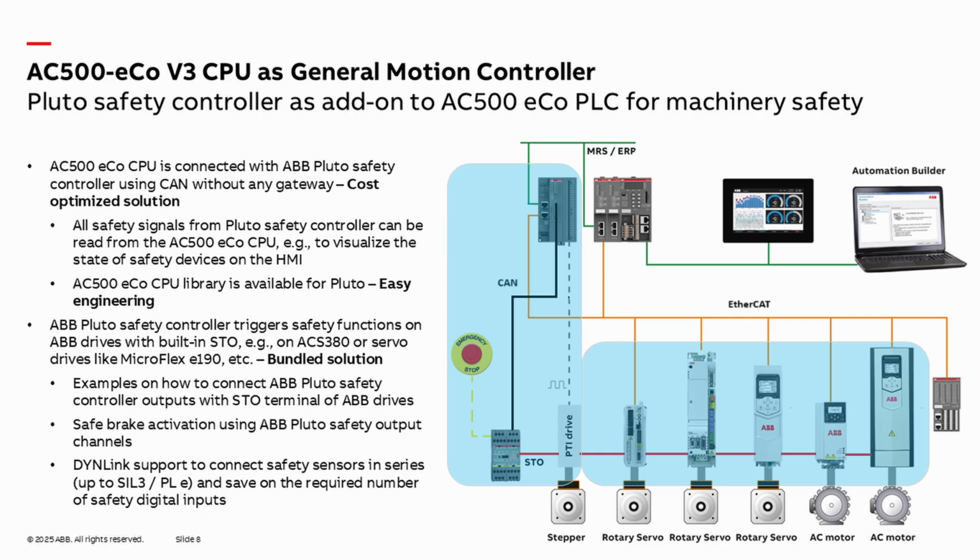So what we see here is completely new, because before you would normally need a gateway if you would like to map the states of the safety signals to the non-safety CPU, and then of course usually you would visualize them somewhere, for example, on the operator panel, HMI, or somewhere else. So typically in custom applications you want to map all safety signals, even if it's a standalone safety, to some central location so you see the states of all of them.